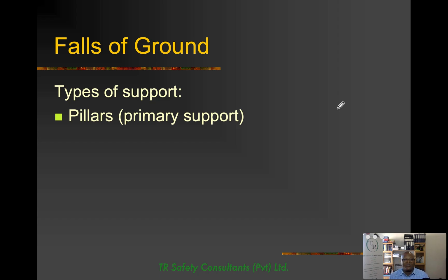And as you know, in pillar extraction, you cut out using your CMs or whatever. You cut out the pillars and you leave some sections standing, because that acts as a primary support. Then you can come and extract those and let the ground fall as you are exploiting the coal that you have left in the pillars. So I'm sure in this disaster, when they were advancing, they were extracting too much in terms of the ratio of the pillars they were leaving and what they were extracting.